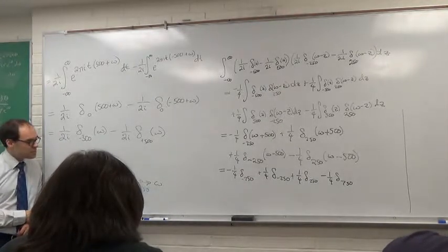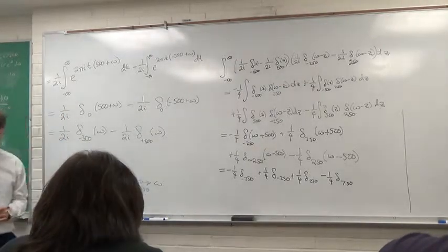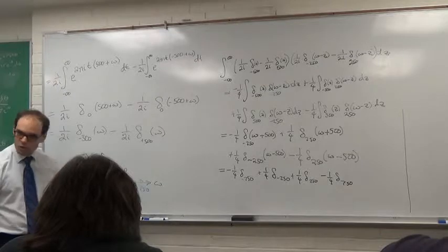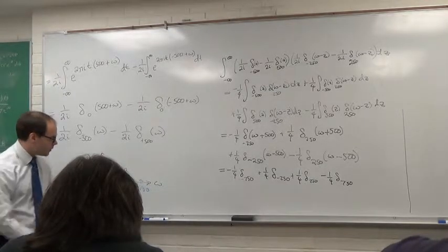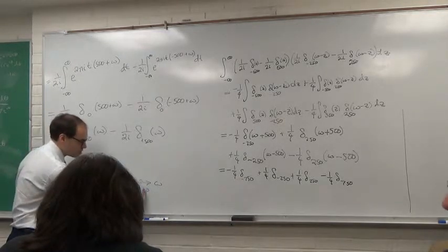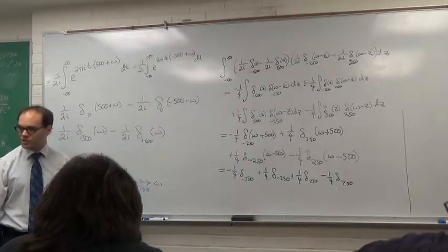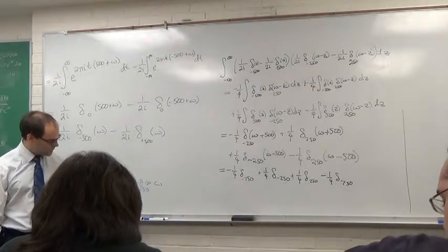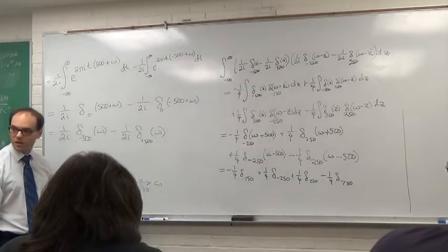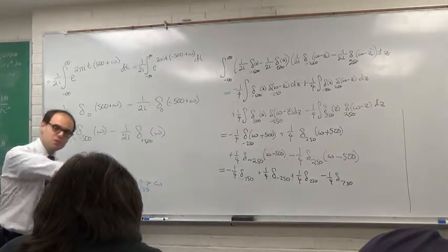This is used in radios because you'll have the signal you're actually interested in, way out here high in radio frequency land, megahertz. You'll have another frequency that you use to tune the radio. It's a local oscillator that will set that frequency. This makes amplitude modulation work. You will tune this frequency so it matches up with the center frequency there. The sum will be way off at even higher frequencies, but what's the difference going to be? Kind of close to 0. In particular, it means they'll be in the audio range. So this is how radios operate. They multiply these signals together to move the signals around.